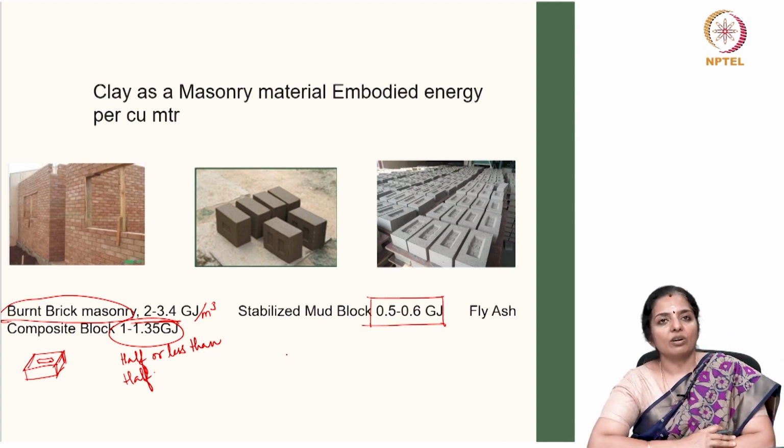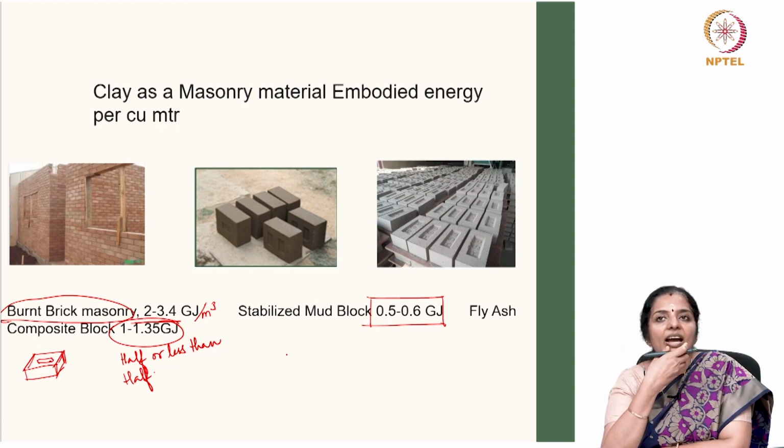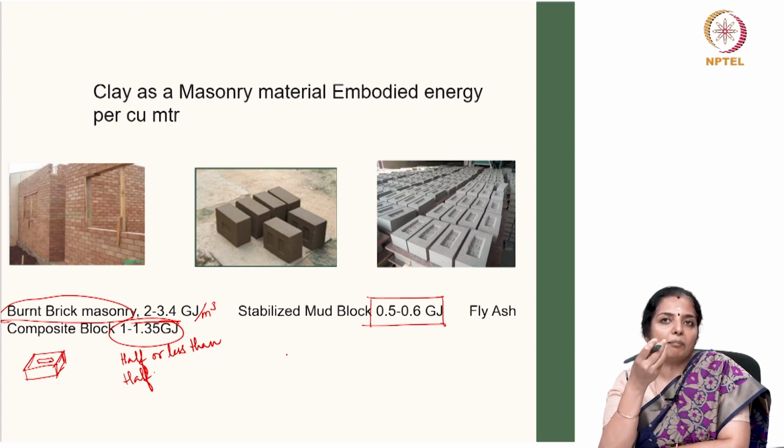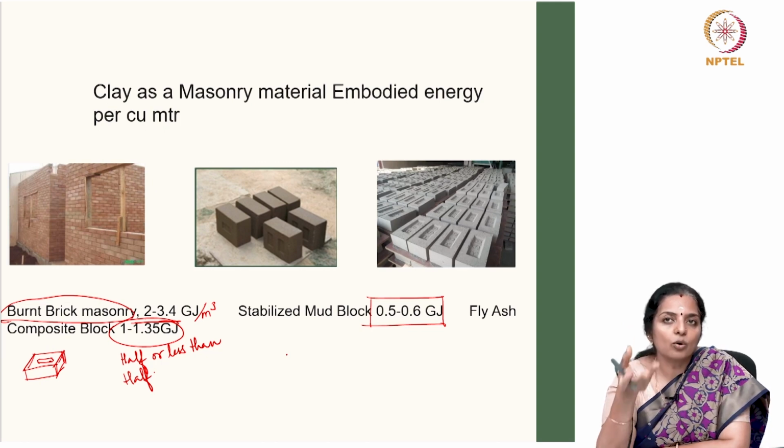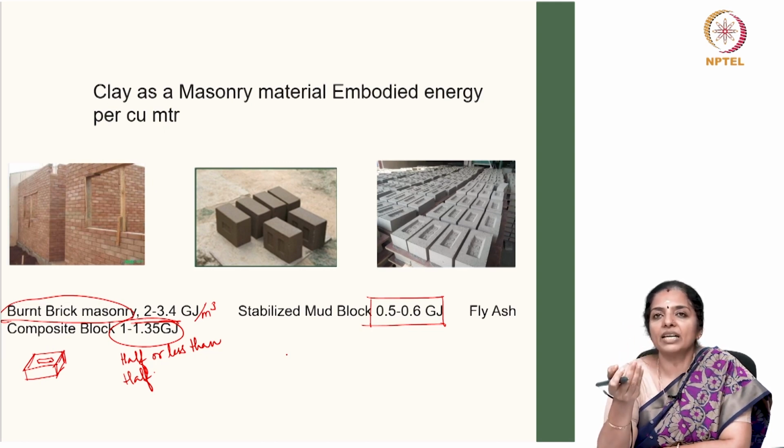Burnt bricks are basically manufactured by burning the bricks at high temperature. So, you process the clay, and the minerals that are found in the clay undergo irreversible changes which gives strength to the brick. But in this process, it uses high energy. Here, conservation of energy as well as clay mineral resource become important from environmental angle, where when it goes back to the soil, will we be able to retrieve the minerals becomes a question mark.